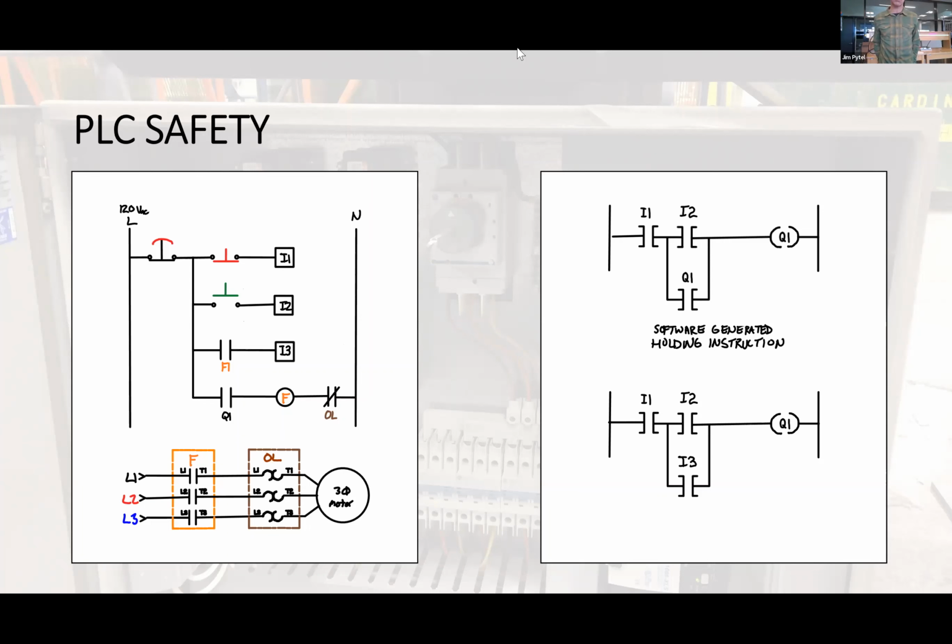Obviously, this is not the case for all scenarios, but I try to get students thinking about this very early in their career. You need to have a way to kill a machine at any point. You always have to have an E-stop to kill inputs and outputs.